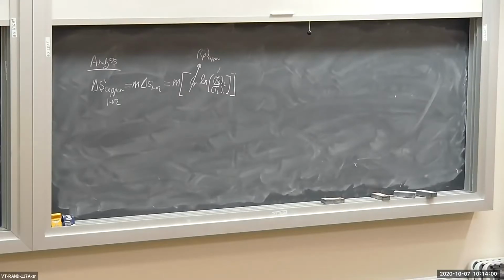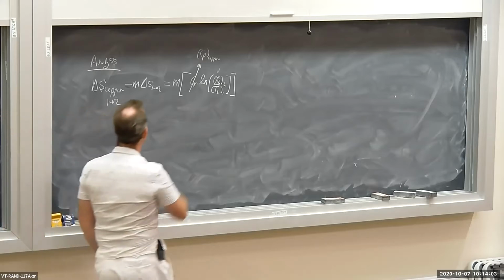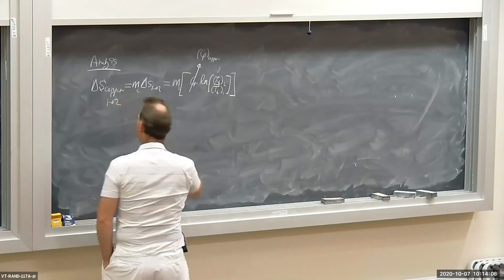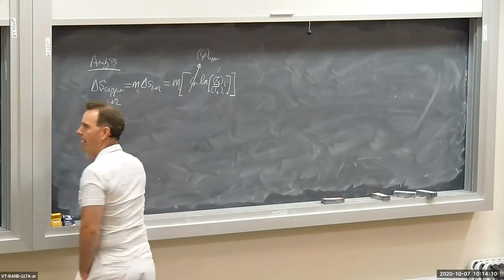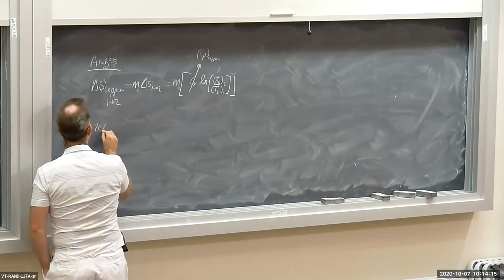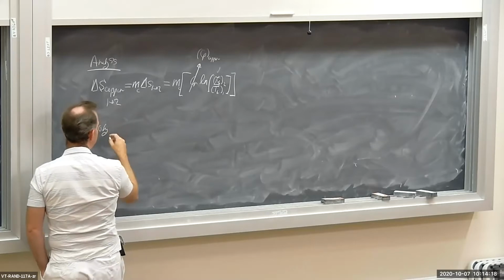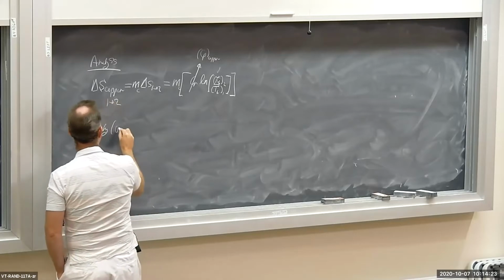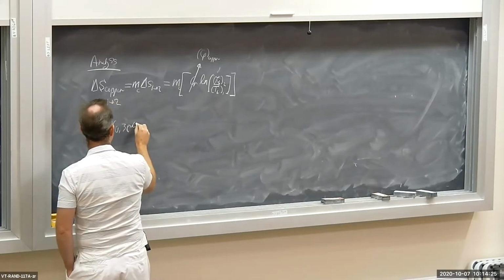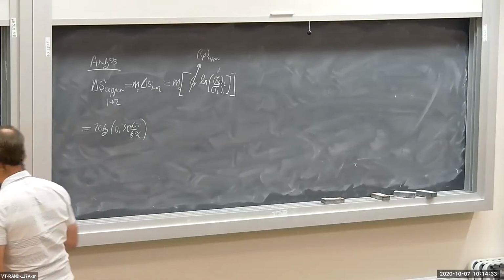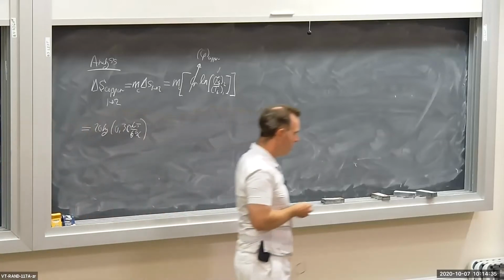Okay, so we have specific heat, we have the temperatures, we have the mass. This is mass for the copper, so I'll put a C here. Okay, let's plug in. I have how much for the copper? 20 kilograms. The specific heat for the copper is 0.38 kilojoule per kilogram degree Kelvin. I hope it's clear that we're assuming constant specific heat when we're doing this problem.